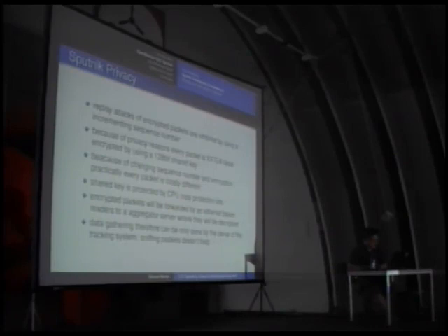Again, the transmission is encrypted using XXTEA block encryption and a 128-bit shared key. We use an incremental sequence number again to make sure that every packet is different, because if only 1 bit swaps in the packet, because of the block encryption, the whole packet changes completely. The shared key is protected by the usual CPU copy protection bits. This is average security, so you can't take a simple program and read out the keys used.